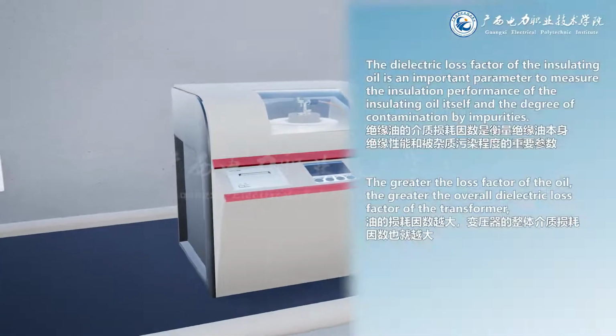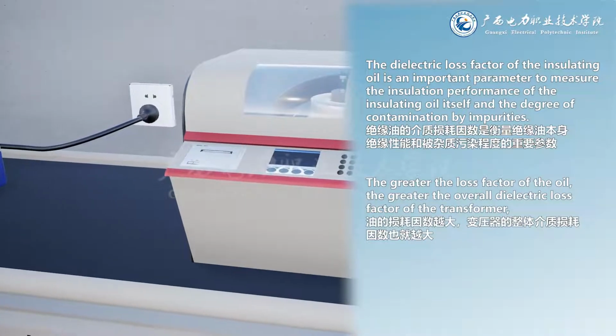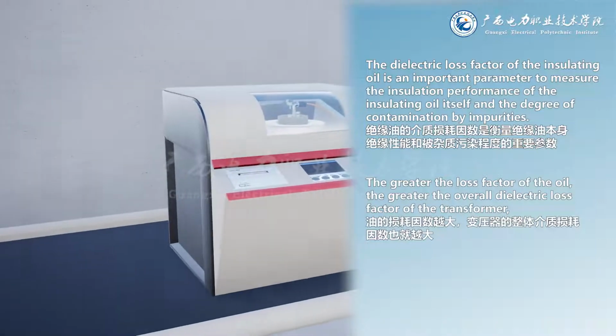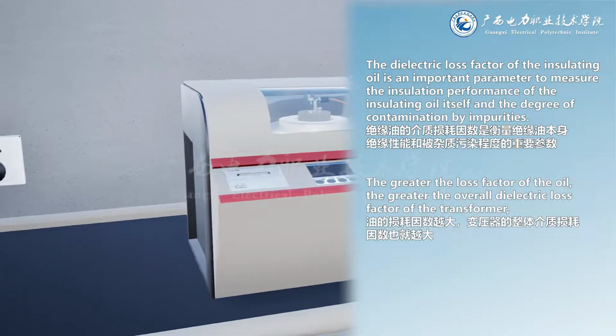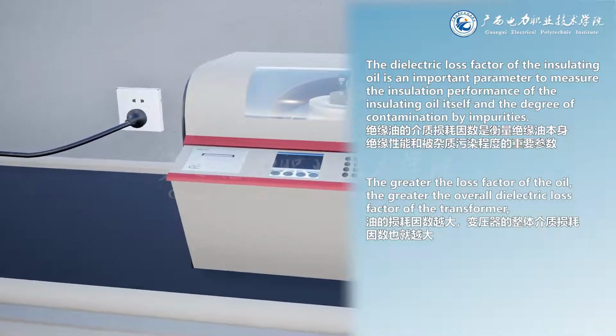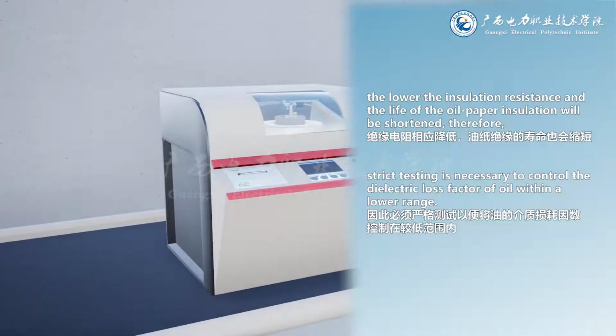The dielectric loss factor of the insulating oil is an important parameter to measure the insulation performance of the insulating oil itself and the degree of contamination by impurities. The greater the loss factor of the oil, the greater the overall dielectric loss factor of the transformer, the lower the insulation resistance and the life of the oil paper insulation will be shortened. Therefore, strict testing is necessary to control the dielectric loss factor of oil within a lower range.